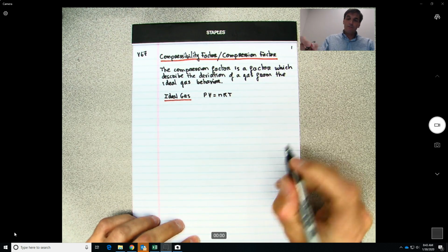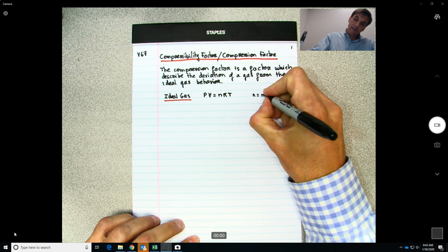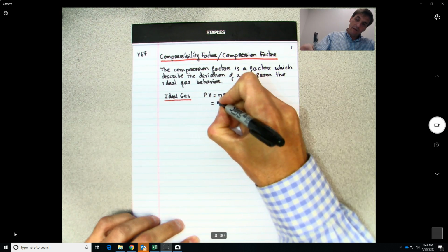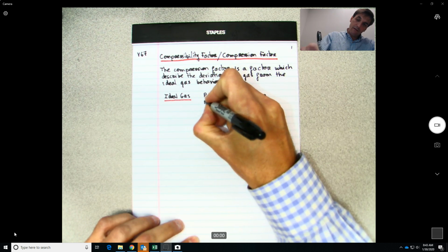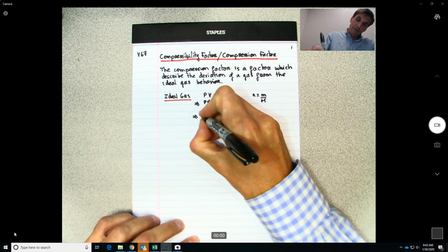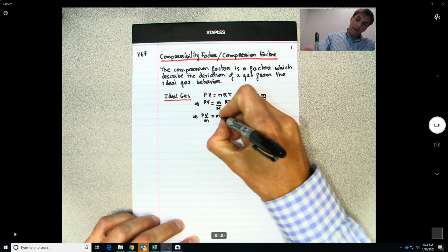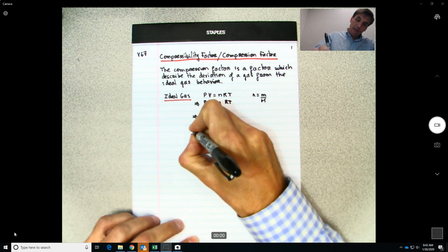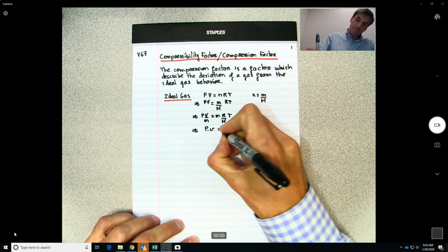So this is one option, but if we use the specific volume, n we know is the mass divided by the molar mass, so this becomes n equal m divided by molar mass, times RT. So we can just rewrite this as PV divided by m equal to mR divided by M times T. And this will give us the second form of the ideal gas relation, which is pressure times specific volume.